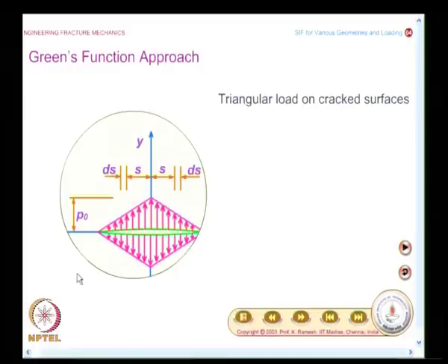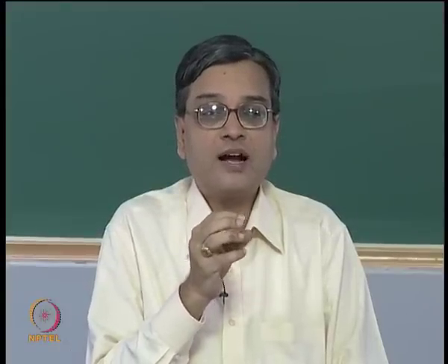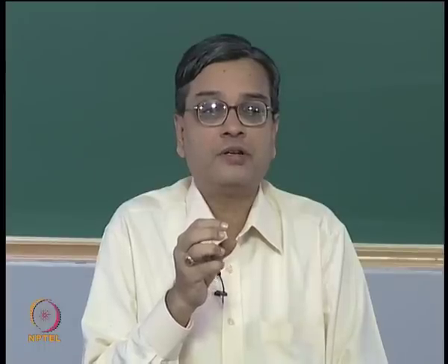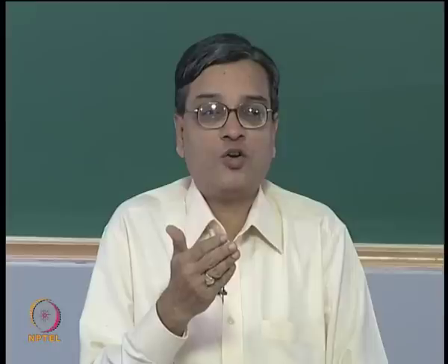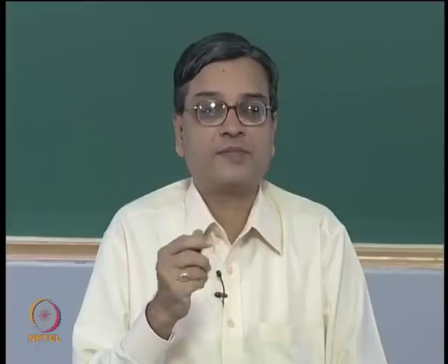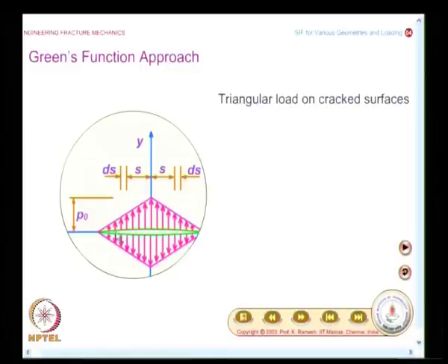And now, you will have to identify which would be the starting point for a solution to this problem, because we have looked at a concentrated load acting at the center of the crack. Then we saw two symmetric loads acting on the faces of the crack. Then we saw an asymmetric load, and if you look at the loading here, the loading is symmetric. So, it would be prudent to use the solution that we have got, where you have symmetric loading on the crack faces.